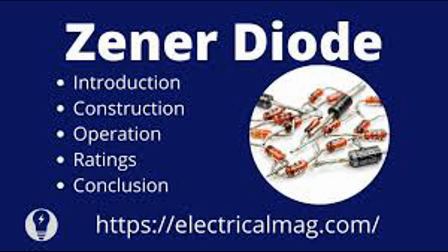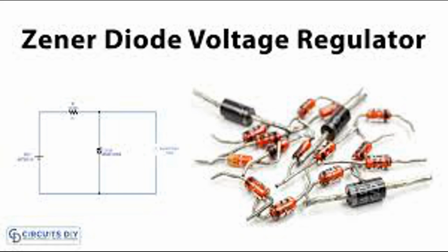Applications. Voltage regulation. Zener diodes are widely used in power supply circuits to provide a stable reference voltage. Over-voltage protection. They protect sensitive electronic components from voltage spikes by clamping the voltage to a safe level. Waveform clipping. In signal processing, Zener diodes can clip the peaks of waveforms to create a desired voltage range. Voltage shifting. They can be used to shift voltage levels in logic circuits.